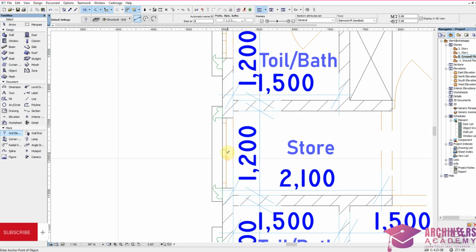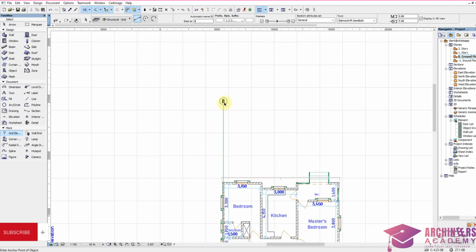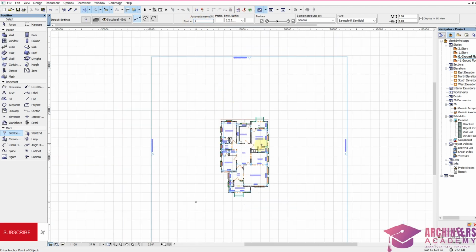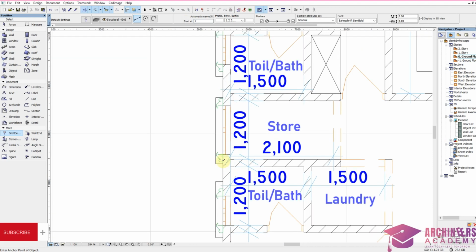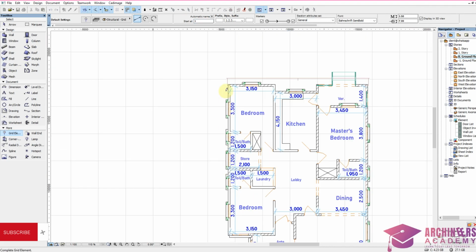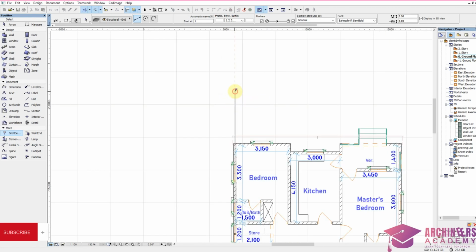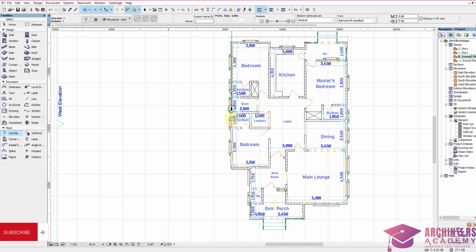So I'll start placing a grid from there because I want mine to be centered. Once I place this, starting from 1, I want my vertical grid to be numbers, while my horizontal grid to be letters. It's just your choice. In the construction side, they'll make reference to what you have done. So my vertical grid is now numbers, and this first one is 1.